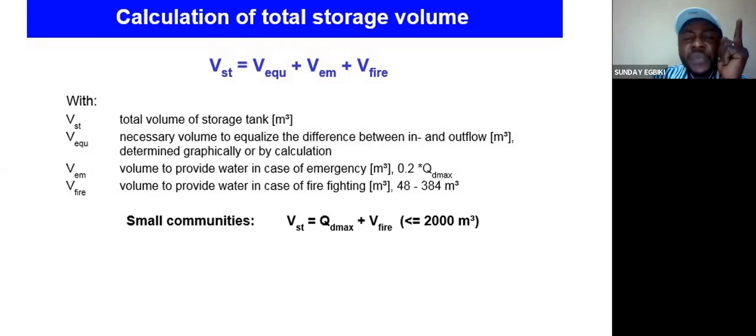The way we consume water every day is not constant. But the rate at which the pump moves water from the water source to the overhead tank through the transmission pipe is constant. As a result, if you take it cumulatively, you are going to have a straight line graph. But the way we consume water in the morning is not the way we consume water in the afternoon or in the evening.